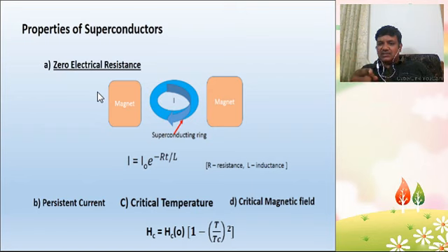So, it is going to be there. Because of this constant current, there is a constant magnetic field. Understand? Constant magnetic field, and because of this constant magnetic field, it will induce some flux. If there is a change in the magnetic field, it will induce an EMF in the neighboring test coil.